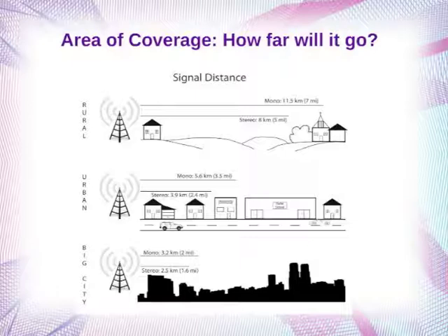R3 calculates this in 2 different ways. This is pretty technical, so I won't go into the technical calculation. Let me say that on the frequencies available page, the one with the green and yellow and red checkboxes and the frequencies, the clearest signal distance does not take into account the interference from second adjacent stations. That's because many of us are going to have to be putting our LPFMs on top of second adjacent stations anyway, and getting those DU waivers, which if you look in there, they're the yellow channels with the PZ equals something or other.